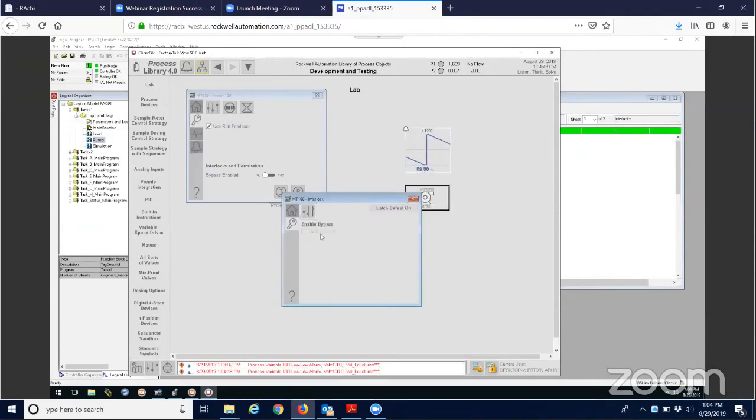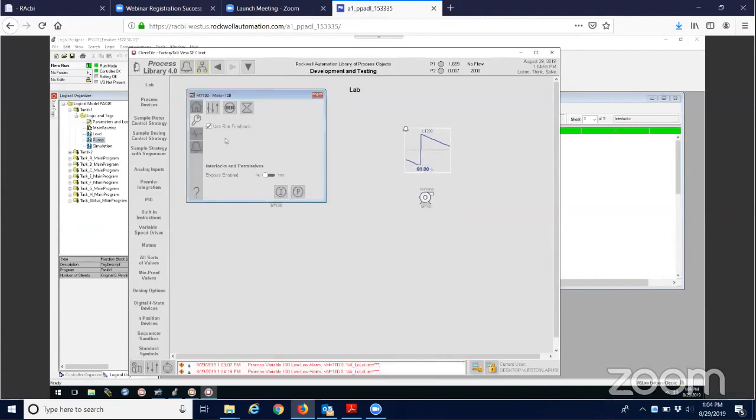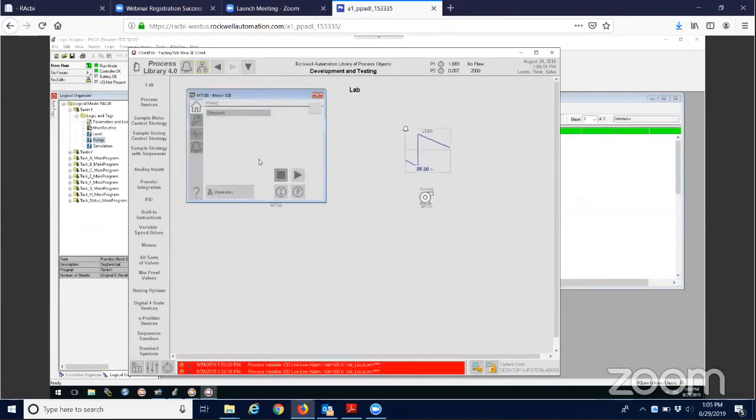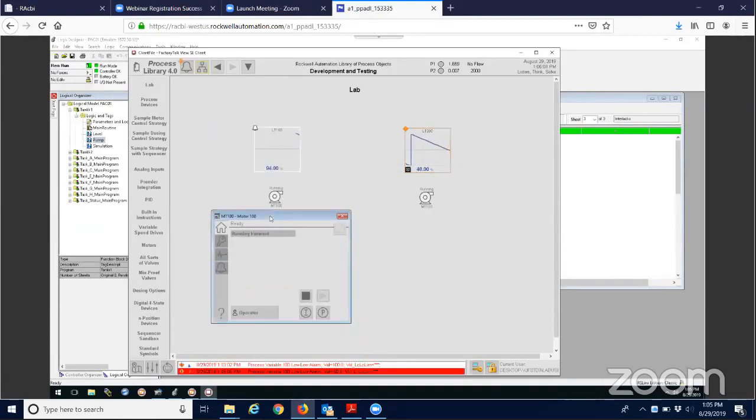Okay, so now that's there. I also did check the must reset, but I don't know. I think I'll have to run through this again before I actually have to reset it. So now when I run through this, it'll stop and then I'll have to actually reset it, so take my word for it. But anyway, that's how you can add a piece of logic while you're adding an interlock.